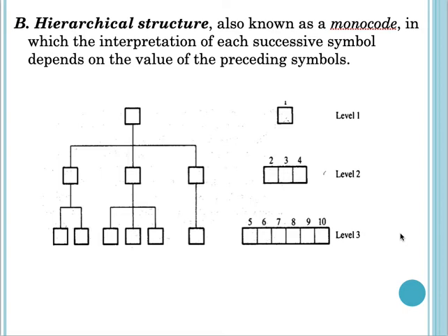The first digit, 0 to 9, divides the part into major groups such as machined parts, cast parts, forged parts, etc. The second digit may subdivide the machined parts into rotational and non-rotational parts, and the third and subsequent digits may partition the machined parts into subgroups.